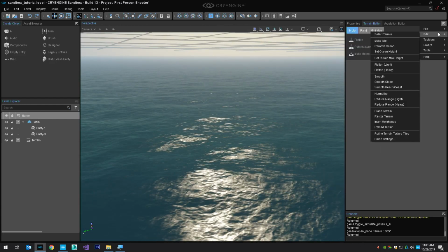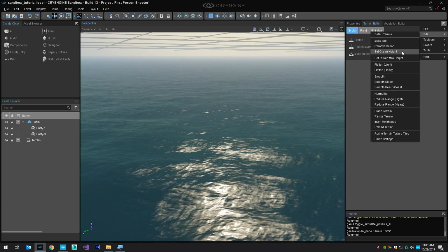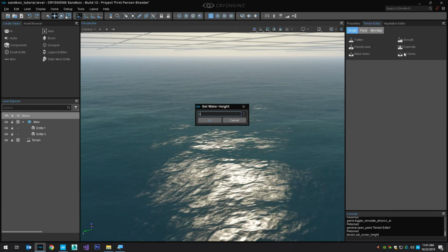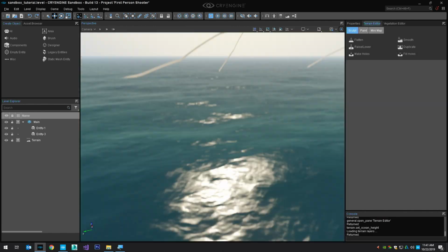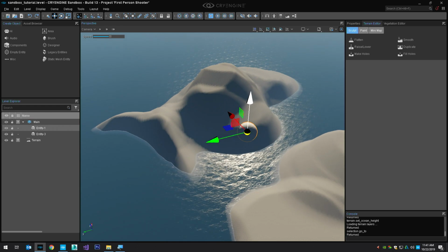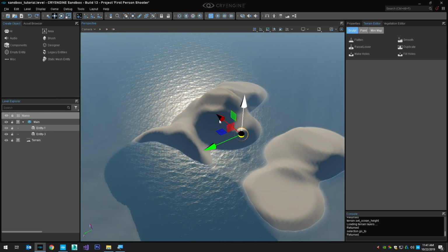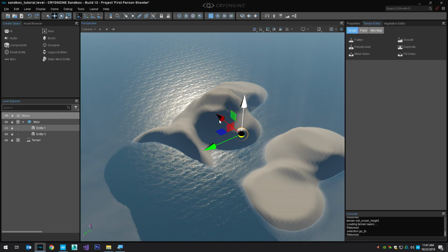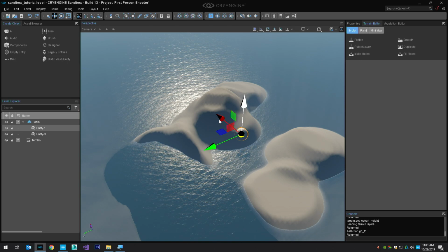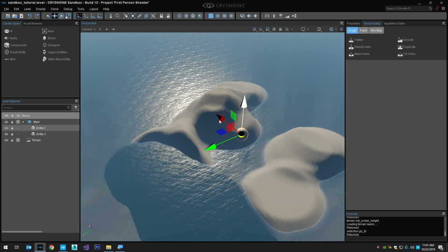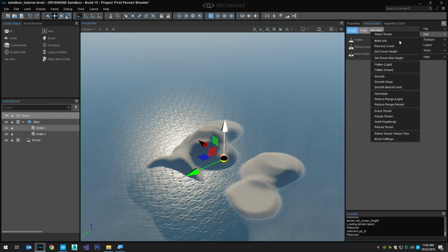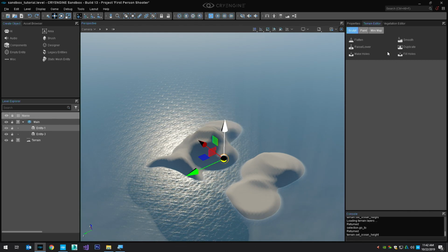So in this menu here, Edit, I have Set Ocean Height. For instance, my terrain is at 32 meters right now. If I set the ocean higher than that, I'm going to try maybe 34, and come back up to one of my entities. Since I made some hills here, you'll see that now I have kind of an island. So only the parts that I raised up are visible, and the rest of the terrain is now below the water because I moved the ocean up to 34 meters high. You can do minus 100,000, deeper than the real ocean. You can also generate data procedurally. I'm going to go ahead and set my ocean back to 16, where it was.